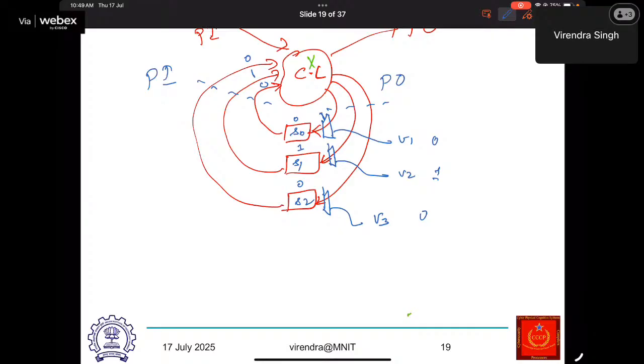That I can reduce, because I can load all these at the same time. So therefore, I can reduce this number to only 1. I can tie up all these. So I say this as a test enable. TE is a test enable. When I'm testing, in that case, I can put this test enable equal to 1, and then I can load all these simultaneously. So now it needs 4 different primary inputs.